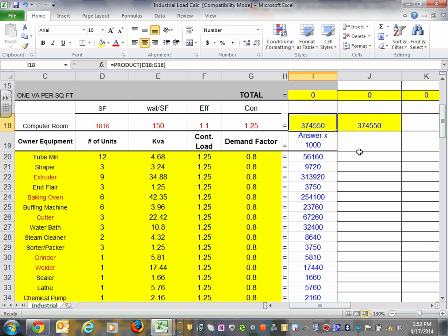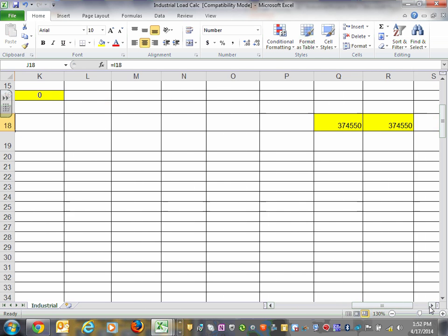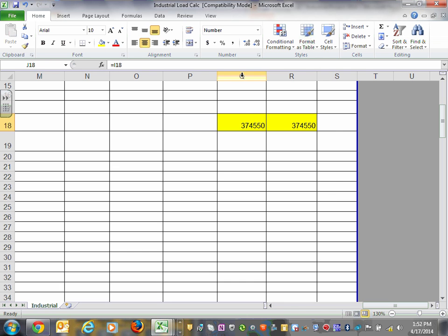So we're allocating, gentlemen, 375 kVA for my data center. I pulled this under the switchgear, you can see, and I'm going to pull it all the way down to my PDU, under my PDU, and under my UPS on my PDU. These are the numbers I'm going to be sizing my UPS and my PDU from the get-go. Does that make sense? So my PDUs and UPSs, for this particular step of the process.